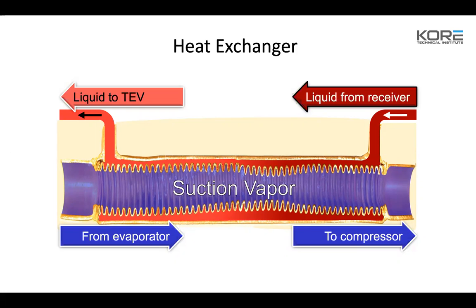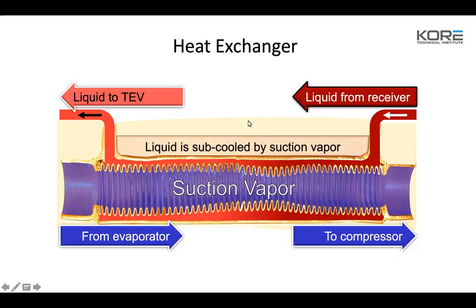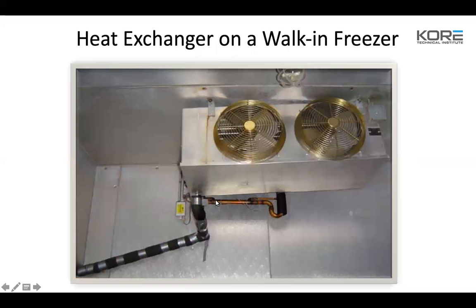When you're dealing with these types of heat exchangers, a lot of times this inner wall will crack because it's ribbed, from heat and cool, and it'll start dumping liquid directly because liquid is the higher pressure of the two. It'll start dumping liquid refrigerant right into the suction line and sending it directly back to the compressor. So right here is a picture of that. Like I said, pretty close to the metering device and inside the cooler.